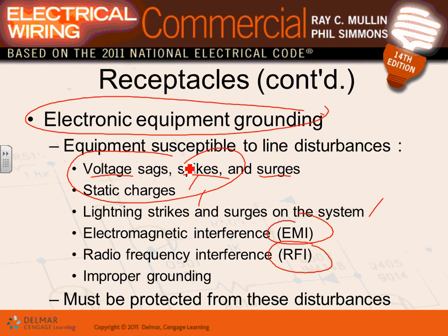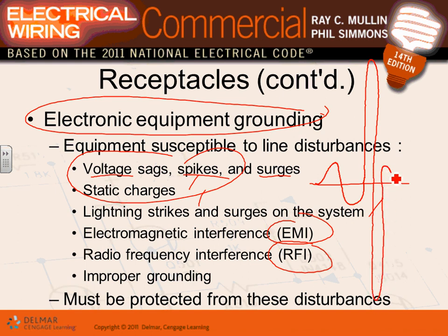In most of this equipment, they have surge protective devices. If the signal is coming like this, and all of a sudden a lightning strike hits, the voltage goes so high, and then goes back again to normal. See that voltage? That means the transmission line got hit by lightning. It pumps the voltage so high. What they do is they have a surge protective device that takes the voltage, actually the current, and sucks it down to the ground.